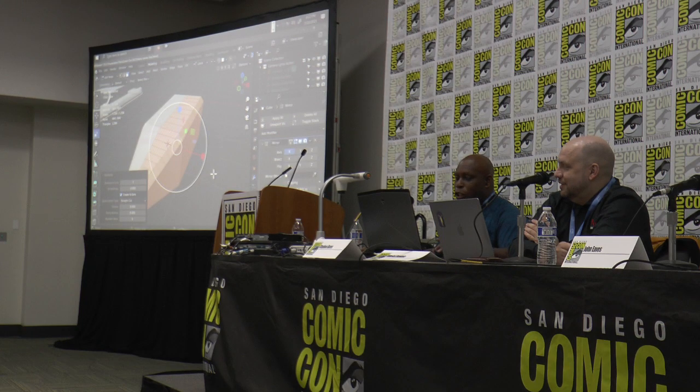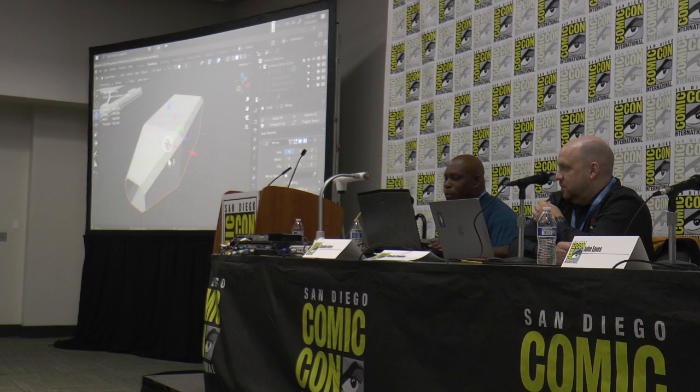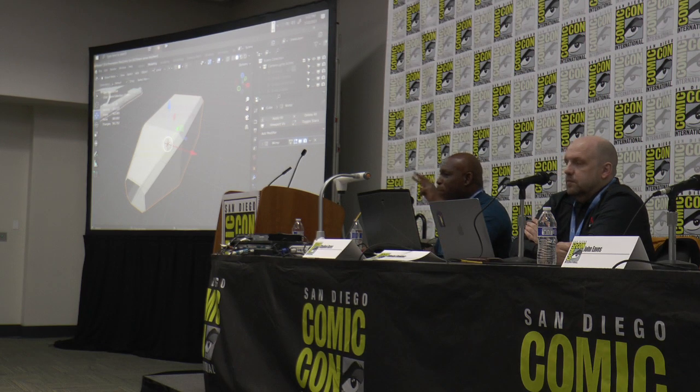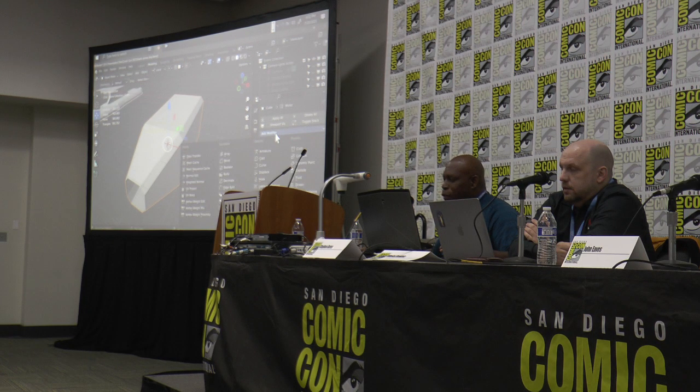Now, we're going to add more modifiers, because we're going to make the grout now. This is going to be interesting, so watch this. Tab key, object mode, we're going to add a few more modifiers. These 3 modifiers are going to be the key to adding grout. And from this point on, once you have those 3 modifiers, you can just draw your grouting exactly where you want it to be. So, my first modifier is going to be edge split.